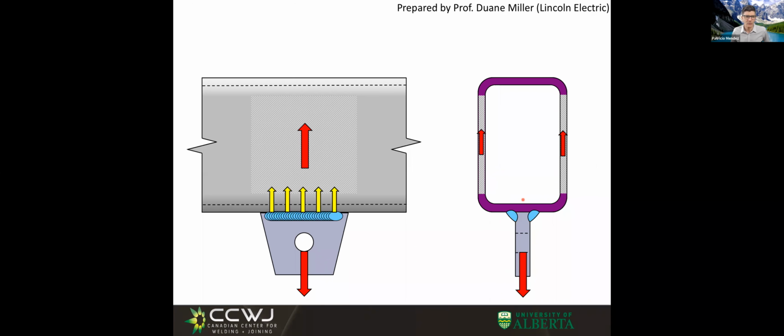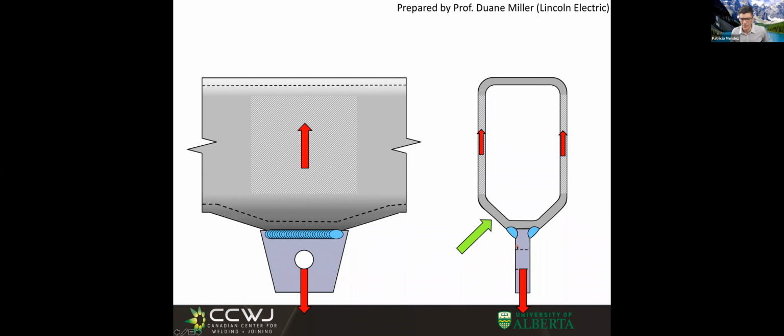Although the weld would be distributed in that direction, or we think so, when we pull, this is going to deform this way. We don't see it with the eye, but it does deform this way. And what is happening? We're opening the toes, and that's bad news. Never a good idea. And the start and the end of the weld is also going to be stressed out. We don't want to do that.